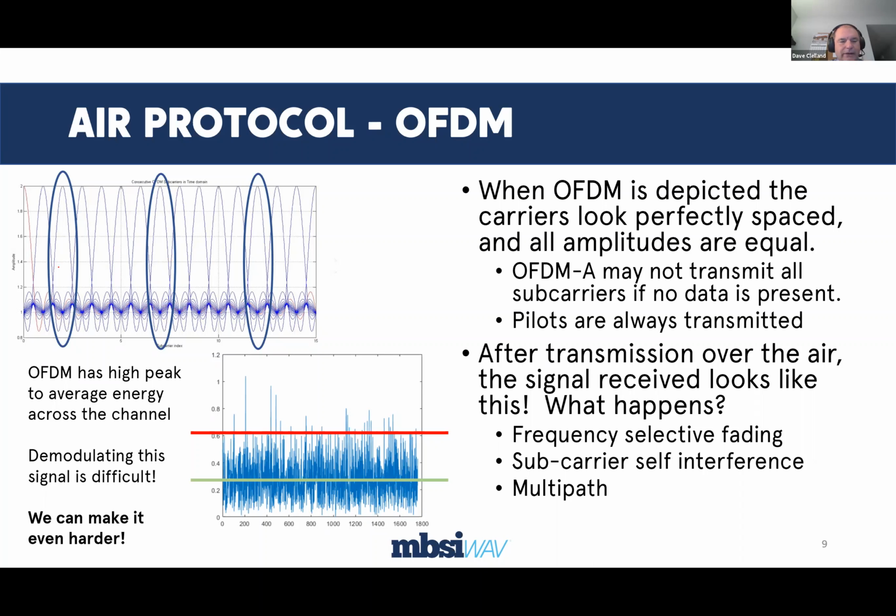As the channel is transmitted, some of them are carrying the data for your subscriber, and some of them are pilots that the receiver at the other end, whether it's in the uplink or the downlink, uses to synchronize to that particular signal, so that the subscriber module knows where the location of each of these pilots are. So it knows that this is a pilot, and then these carriers contain data, and this is another pilot, and so this is what synchronization is in OFDM. The receiver knows exactly what the content of each of these carriers happens to be.